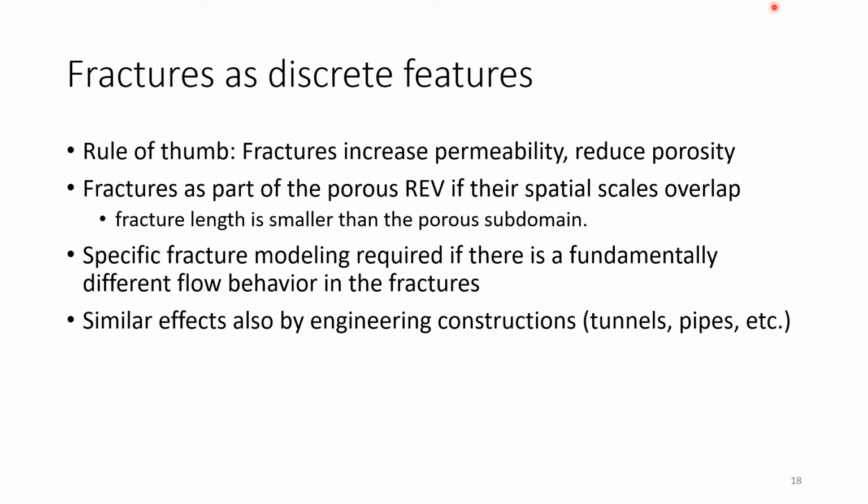The second specific feature of groundwater flow modeling, which requires our attention, are fractures. So fractures are usually known to increase hydraulic conductivity, can be associated with a reduced porosity, though this depends. There also is literature divided. It depends on a lot of different factors.